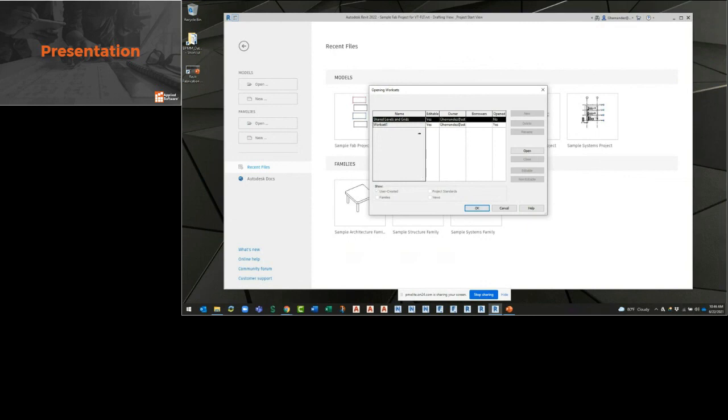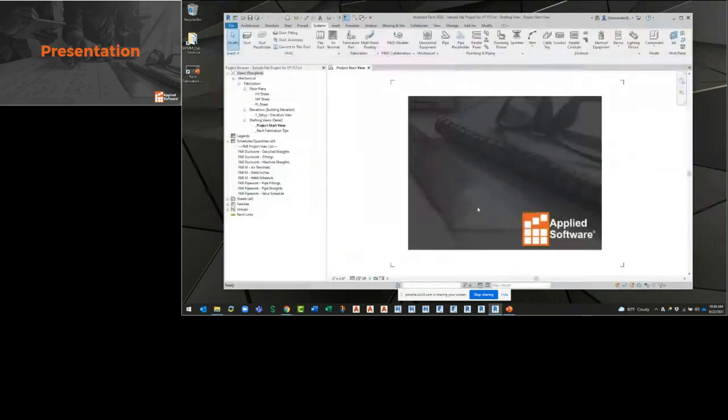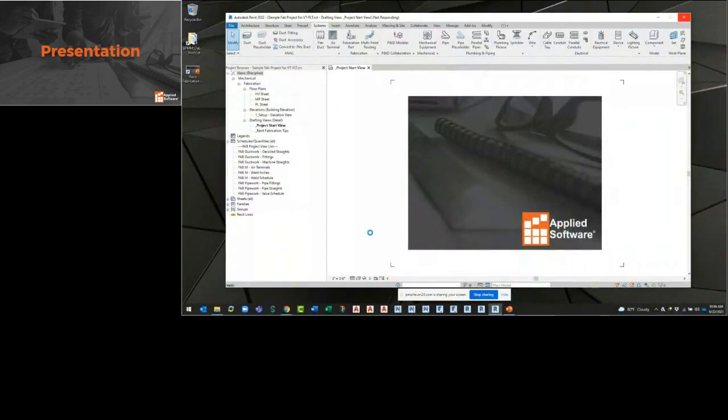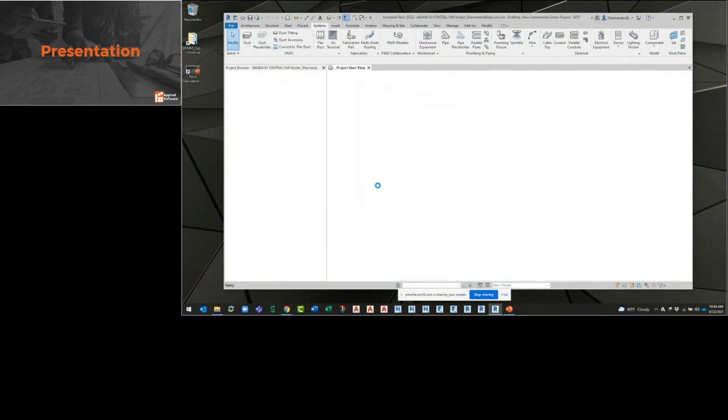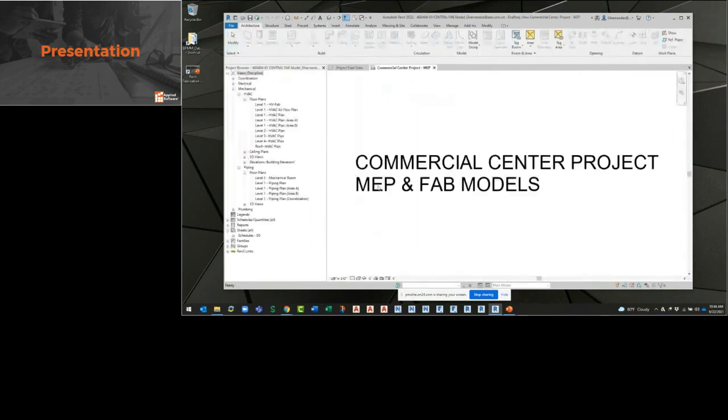So if it's level 3, I can open up just level 3 and not the other stuff. So again, it opens up that much faster, okay? So work sets in your projects help with optimization or performance. When it comes to that kind of stuff, you can use a demand load and open up just what you need. Or if you're troubleshooting, you can open up everything in the project, okay?